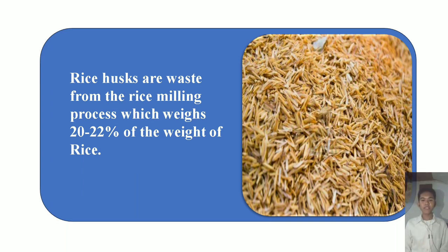Rice husk can be used as the fine aggregate in porous concrete materials. It is used as a unique and effective road material that is environmentally friendly. It captured rainwater and allowed rainwater to seep into the ground. Porous concrete material can help replenish groundwater reserves and reduce surface runoff. When applied to the road shoulder, the water runoff from the road can be absorbed into the ground and reduce the drainage channel's water discharge.